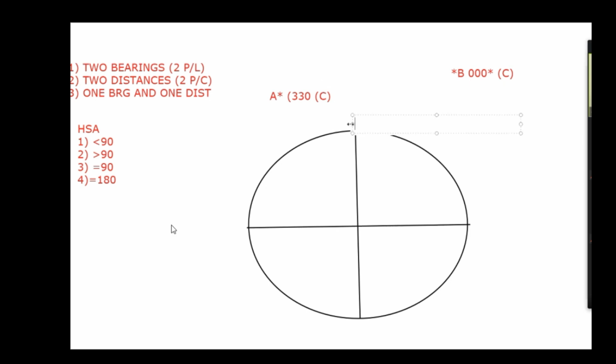To get the compass bearings, we should know the compass north. Compass north is not given in the chart. So all the degrees graduated on the compass rose are with respect to the true north. This is your 180 and 270, and every degree is also marked. From 0 to 90 all are marked. I am not showing it.